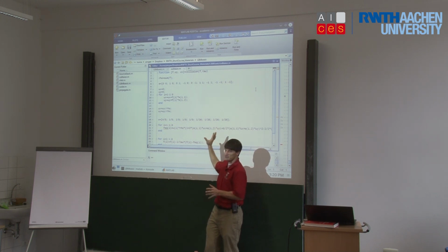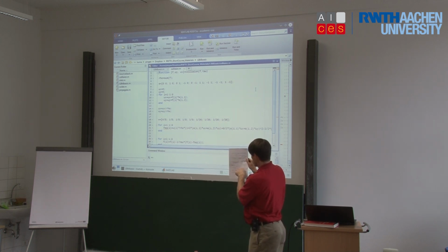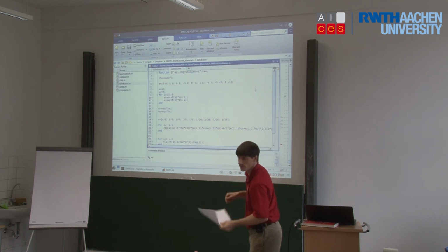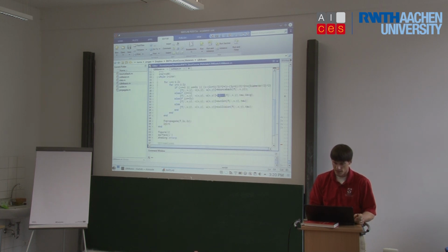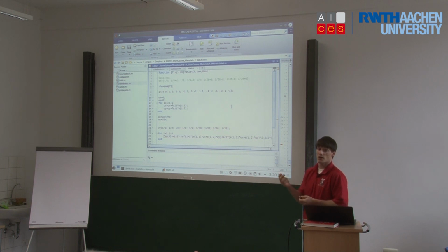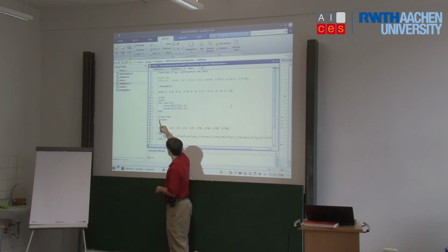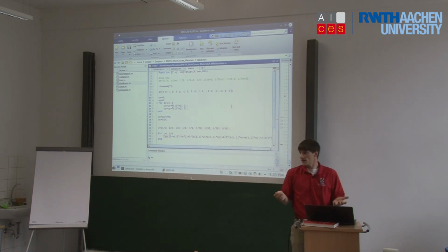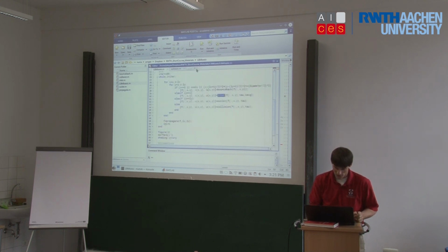Okay. So this is very explicitly written, and it's basically the implementation of exactly the equation right here in the notes, and this equilibrium distribution function. Now, let's say we have an inlet. What we want to do oftentimes is prescribe the velocity at the inlet. So all we can do is take the same collision function, but right here, let's say we want to prescribe a velocity in the y direction, we just overwrite the calculated velocity with the velocity that we want it to be. So that would be an inlet condition. And there are more precise ways of doing it, but this is the easiest way to implement it.